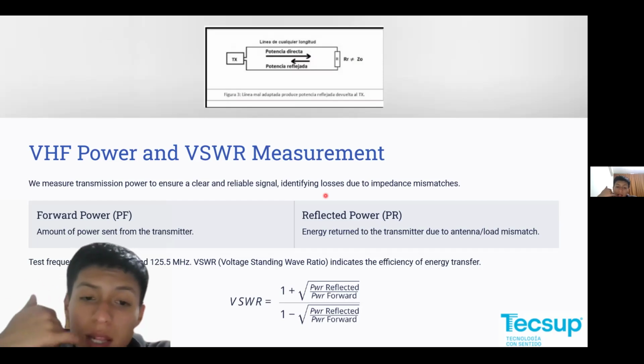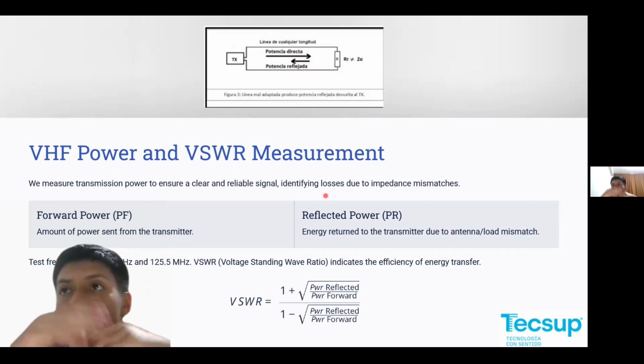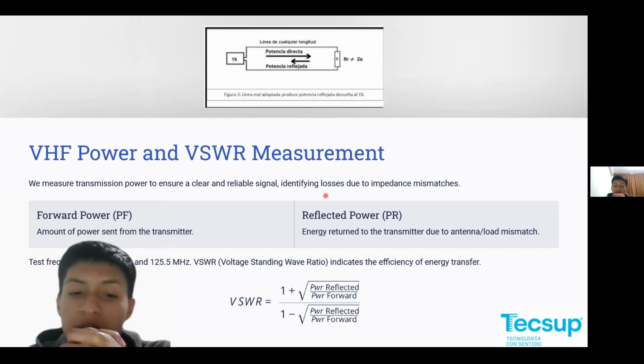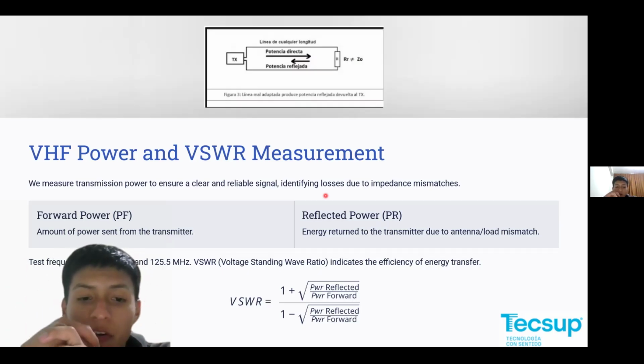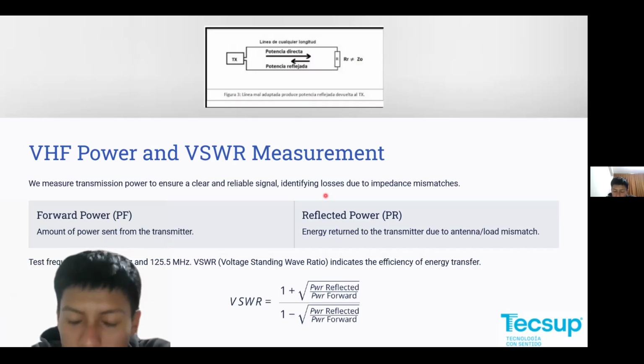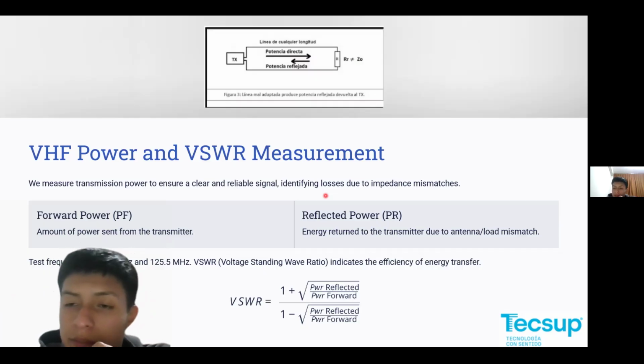For the audio level limit is more or less minus 66 dBm for complete fade out. Technically, this shows that the receiver meets manufacturer specification and can process very weak signals.